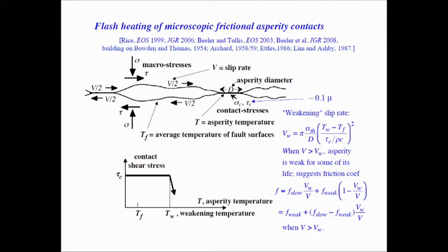So the shear stress is indirectly inferred to be very high too, of the order of 1/10 of the elastic shear modulus. So these are enormous stresses. That means that as we slide, we generate a lot of heat. And if we slide fast, that heat does not have time to diffuse away, which means the temperature goes up. So there's an elementary model of this process, which just imagines that you get the contact hot enough to weaken.